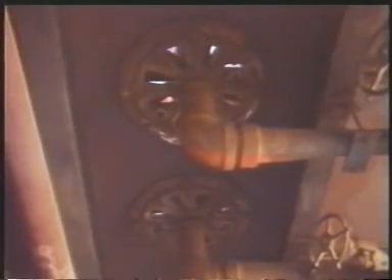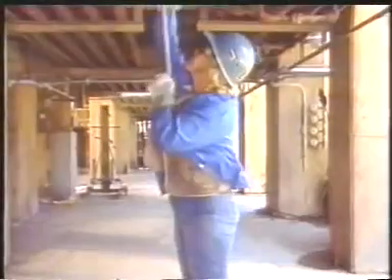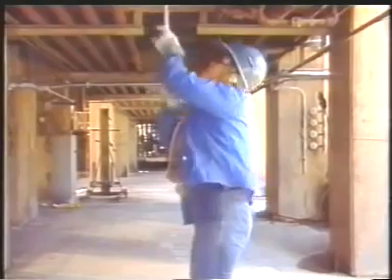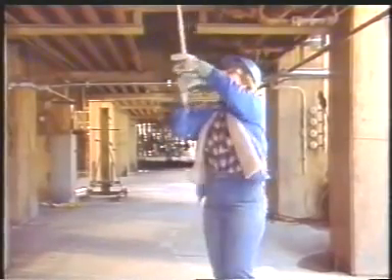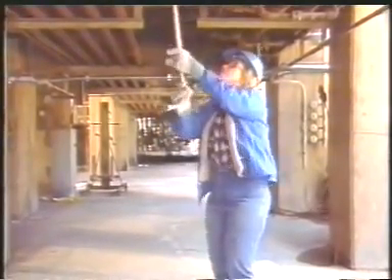The air registers are the main control of air to the furnace. When the furnace is lit, the air registers should be adjusted to allow the proper amount of air to each burner. The air registers on out-of-service burners should be closed to prevent excess air from entering the furnace. Peepholes should also be kept closed to prevent excess air from entering the furnace.